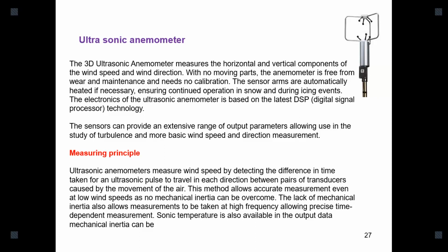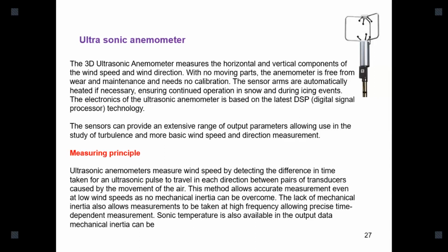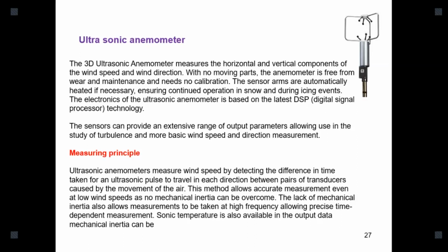Now, the advantage of these ultrasonic anemometers is that the moment of inertia effect is no more there. These ultrasonic anemometers can be used for instantaneous wind measurements, that means quick measurements, that means gust wind variations. The quick variations can be found out here. As well, we can use these ultrasonic anemometers for control applications. Some wind turbines may require the maximum power point tracking concept, because the real time actual wind speed needs to be measured.